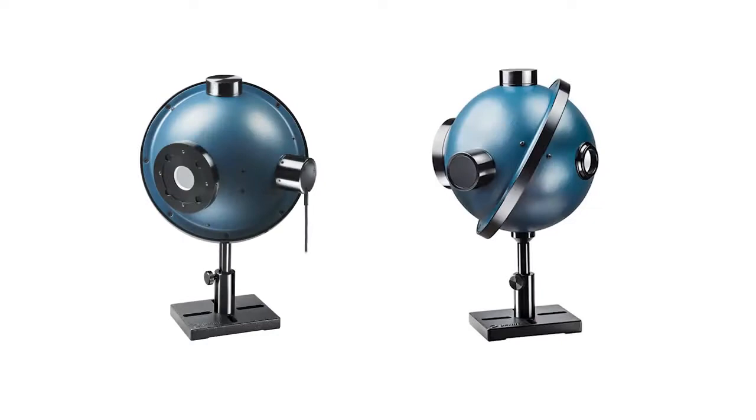Ophir offers a comprehensive set of solutions for accurately measuring VCSEL beams. Let's see how each of these challenges we just looked at is taken care of. 1. Widely diverging beams. Ophir's IS6 family of integrating spheres with integrated power sensors and fully calibrated covers powers from a few hundred nanowatts up to 30 watts, depending on the model, over the spectral ranges relevant for VCSELs.